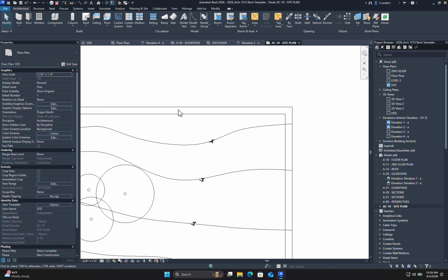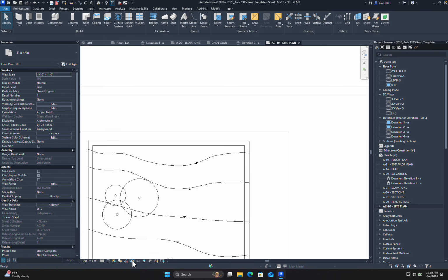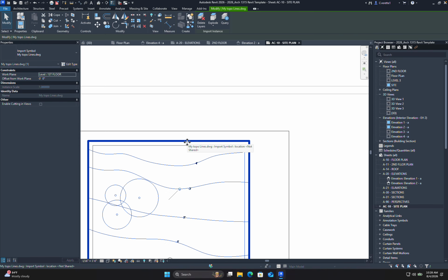If you notice that you have things that are on each other, right? So for instance, let's show my frame. You'll notice that sometimes your frame is on the piece. If you type in tab, you can actually flip through the things that it is. Like in Rhino, when you accidentally click on something and it pulls up a little window that goes, which line are you talking about? Well, Revit has the same thing, but it doesn't show you it. Essentially, it wants you to go through it by clicking on tab.